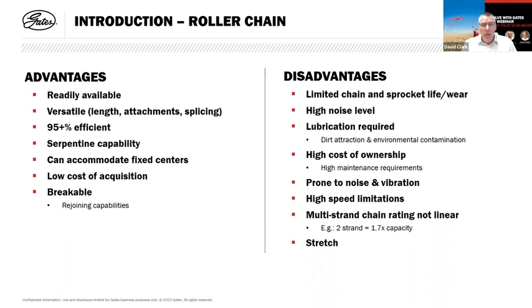On many chains, lubrication is required. There are chains, I think, which have lubrication solutions built in. But again, as you tend to get more and more technology within the chain, your cost is going up. And the vast majority of standard chains still need lubrication, and that can attract and accumulate dirt and environmental contamination, and while giving you an increased lifetime it will still have a detrimental effect.